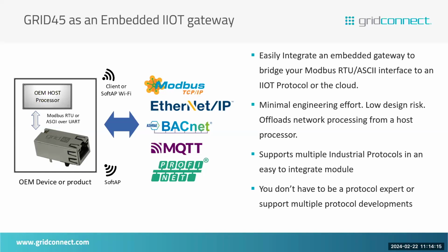That's awesome. Yeah. So there is a certification requirement if I buy a gateway. There are gateways out there, and if you create your own GSD file, then technically you're supposed to be certified by a PI test lab. And there's one in North America, in Johnson City, Tennessee. There are ways that you don't necessarily have to do that if the gateway is already certified. But you have to conform your Modbus device to it. So there are different ways we can do it.